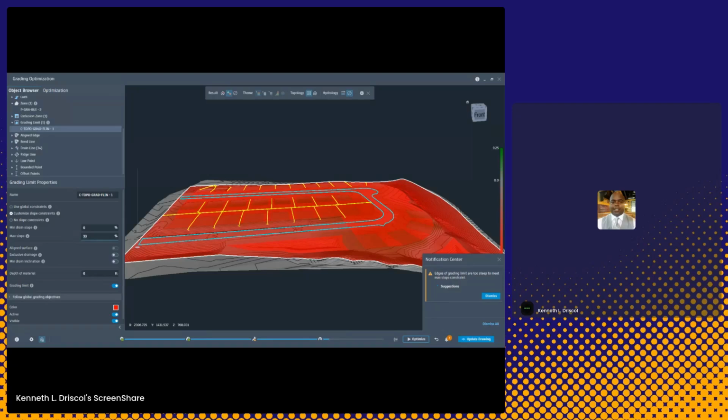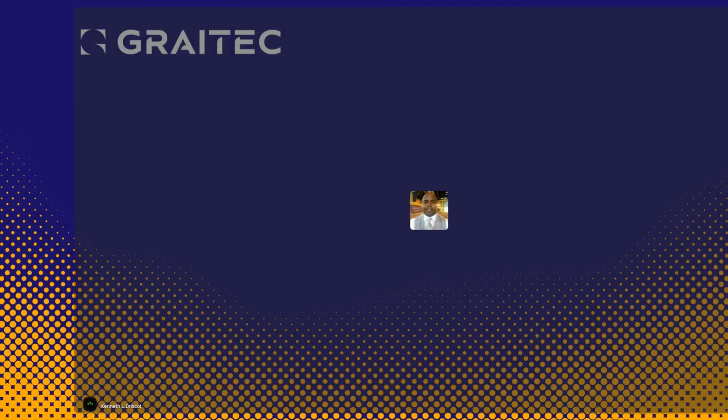So from that, specifically, building pads, parking lots, retaining walls, drain lines, detention ponds, all these things in reference to grading. An overall project, you'll save 70% using grading optimization. And it's not for everything. Because if you were doing a small site with a building pad, and said, I just wanted to grade them, you can do that with feature lines.